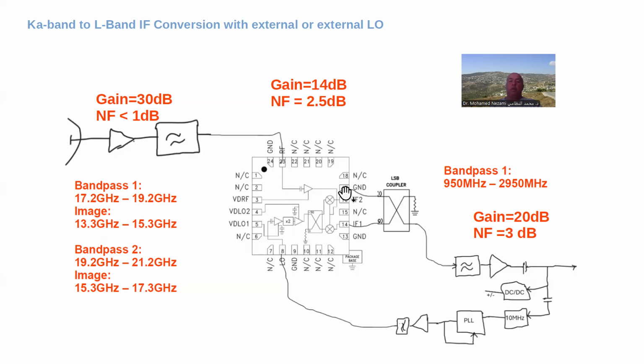If you look at this chip, you will see that the image rejection on the single sideband generation process is specified at 30 dB. But in actuality, when you put this on a board, with the quadrature impairments that you're going to get, you're not going to get more than between 20 to 25 dB of rejection on the image.